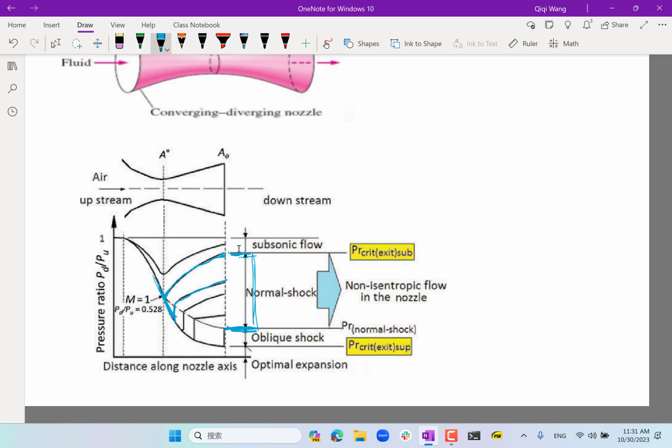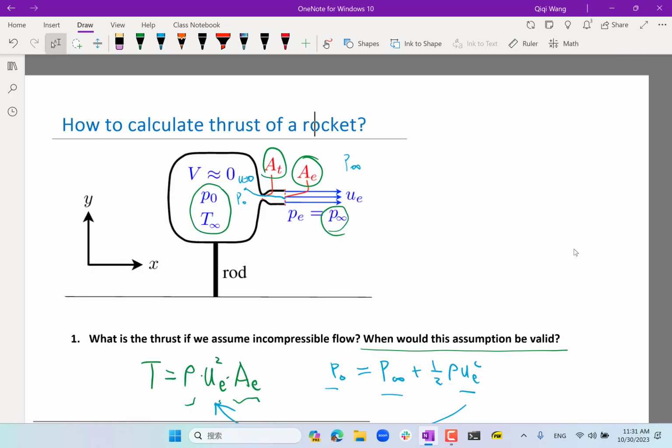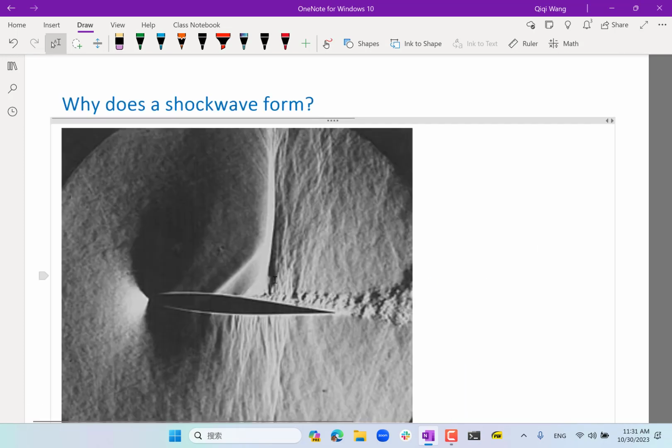And the shock wave is the transition between a supersonic region back to subsonic regions. Okay, and let's actually use two examples. One example is on top of an airfoil. If you draw the streamlines, you're going to see that the streamlines actually resemble a convergent divergent nozzle very much. So, for example, if you look at a stagnation point streamline, it goes like that, right, and follows the contour of the airfoil, and think about another streamline above it.